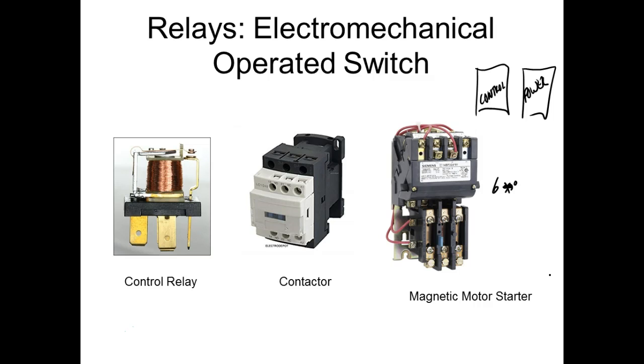We call it forcing. We'll look at forcing on PLCs too. On PLCs we have to go to force contact. But you need to be real careful and understand the consequences of forcing, because you've taken away every safety feature that's built into that system. Right? All the sensors that sense if somebody's slid up there.